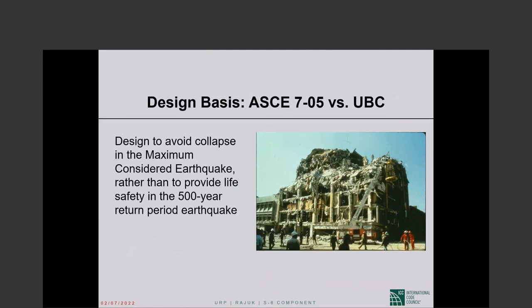Under ASCE 7 and the IBC, we designed to avoid collapse in the maximum considered earthquake, rather than to provide life safety in the 500-year return period earthquake.